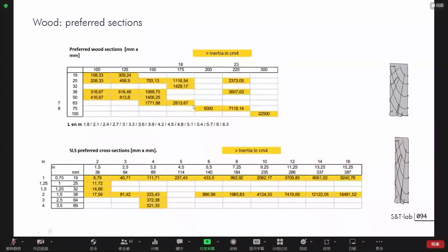In Europe, you have most of the time sections that will be 2 to 3 times higher than the width, and in the American system, it can be up to 10 times. So you have to design the structure totally differently, according to the fact that you will have instabilities that are linked to the very high sections as produced here.